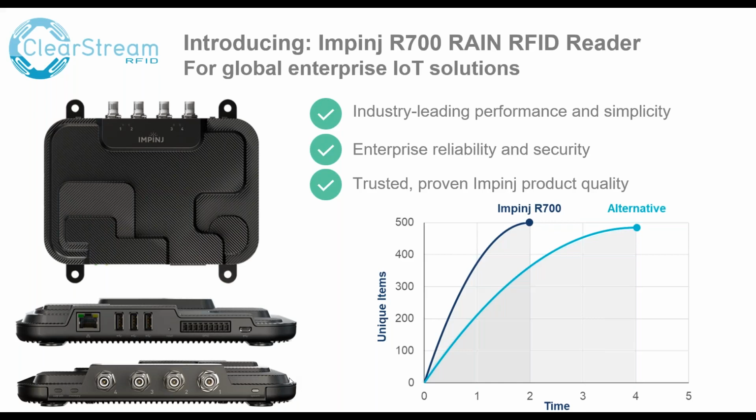So if the reader identifies it's an Impinj chip, it will open up that auto tune feature and try to come up with more RF modes and different power levels to really try and get to read that hard to read tag in that fast manner. So your complex use cases are now offering those hard to read tags being read at a quite faster speed. And of course, this is an option. This option isn't available when it sees that these are not Impinj tag chips. So hence the better together story.